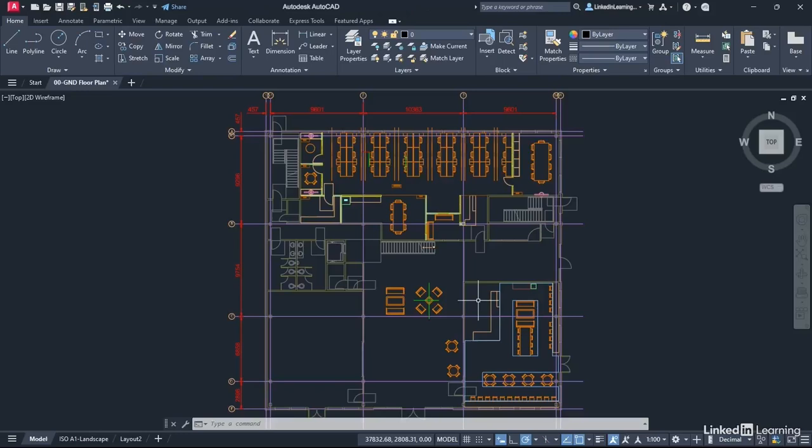But if you've got a really large drawing that you're working on, a massive floor plan, let's say a stately home or a factory, for example, there are going to be areas that you need to go to in that drawing regularly to work on certain things. So what you can do is you can generate what they call named views. Now, these named views are incredibly useful to allow you to navigate your AutoCAD drawings.